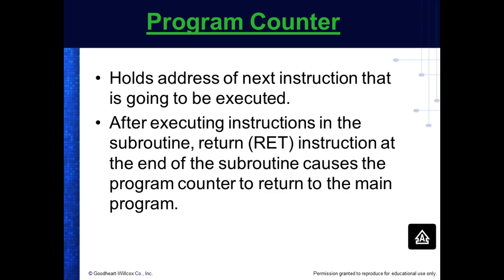They split it up into subroutines, which is really neat because for some reason when the guys set the line up on one side of the room, we moved it over to the other side of the room and the robot messed up all the points. So instead of me trying to go through the whole program and find where those points were, I could just go to the subroutine and keep going through it until I got it running the way I wanted it to. And then I would go to the next one and the next one, which is really what it needs. That made reteaching all those points on that robot program extremely easy.